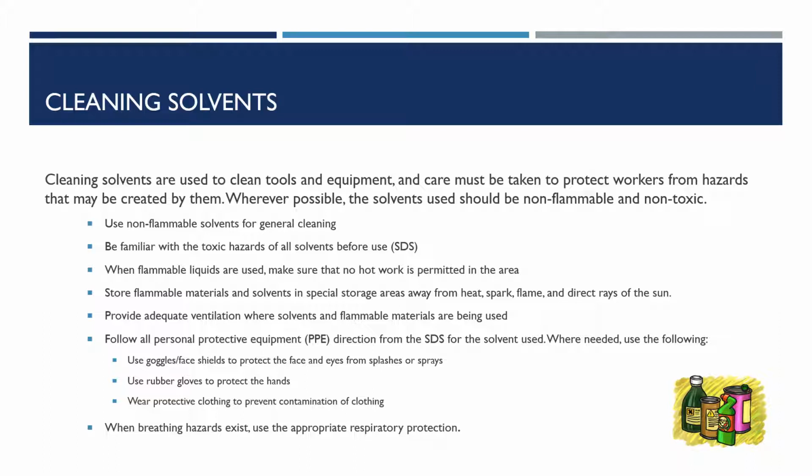Store flammable materials and solvents in special storage areas away from heat, spark, flame, and direct rays of the sun. Provide adequate ventilation where solvents and flammable materials are being used. Follow all personal protective equipment direction from the SDS for the solvent used. Where needed, use the following.